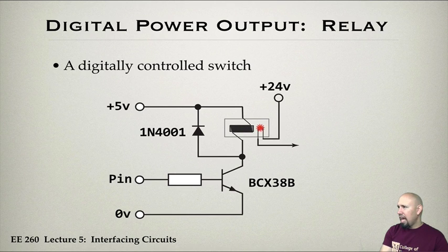What the magnet does is it has these 2 contacts, and one of these is magnetic. Usually this one over here is magnetic, and so when the magnet turns on, this guy gets pulled over and touches the other guy. So you have these 2 contacts and a magnet, and when the magnet turns on, this guy gets pulled down and they touch. They make contact. And when the magnet turns off, then it releases. These contacts can handle more current than these contacts, which can handle more current than this pin. So it's like stages that allow us to do this.